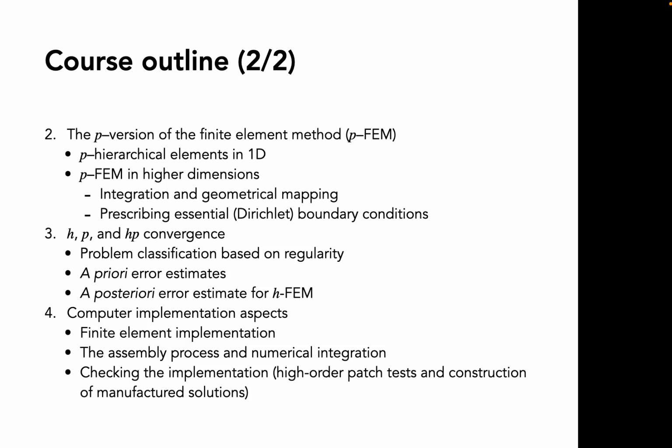So back in the day, if someone knows the Rayleigh-Ritz method, have you heard about the Rayleigh-Ritz? Okay, well, this method basically assumed this type of functions, trigonometric functions, but the problem with this is that the functions have global support, so they are basically spanning the entire domain, right? And therefore, the resulting matrix is a dense matrix that is harder to solve than a sparse matrix, right? So we are not going to look at Rayleigh-Ritz type of approximations in this course.